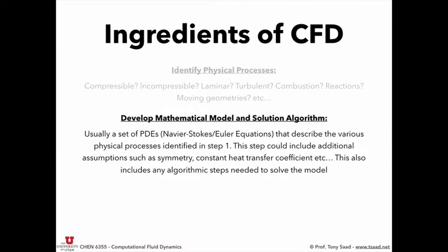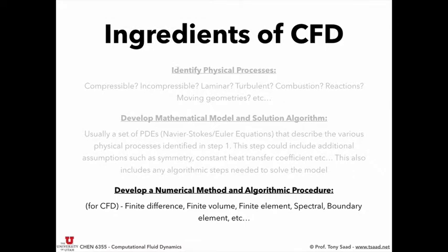And the last step is, in light of the nature of these equations: is convection dominant? Is your Reynolds number high or low? Is diffusion dominant in your problem? In light of those equations of your mathematical model, you want to pick the correct numerical method and correct properties of the numerical method to solve these equations.